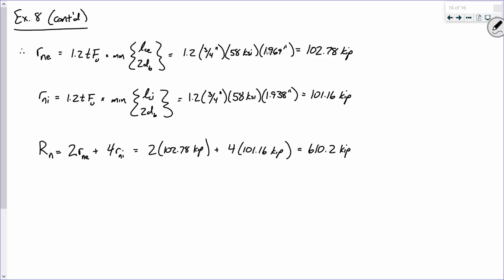All right. What did I forget? There you go. Now, what is phi? 0.75. There we go. So therefore, phi Rn is 0.75 times 610.2. So we'll just put that over here. So phi Rn comes out to be what? 457.7, is that what you said? All right, do I have a second on that? There we go.